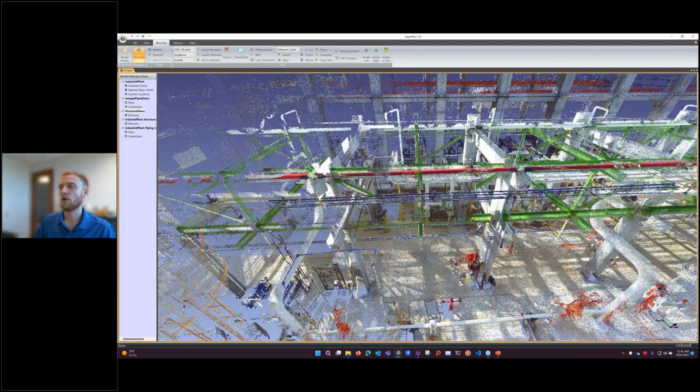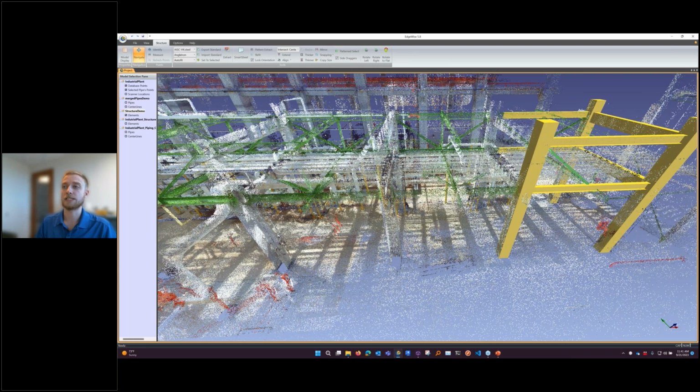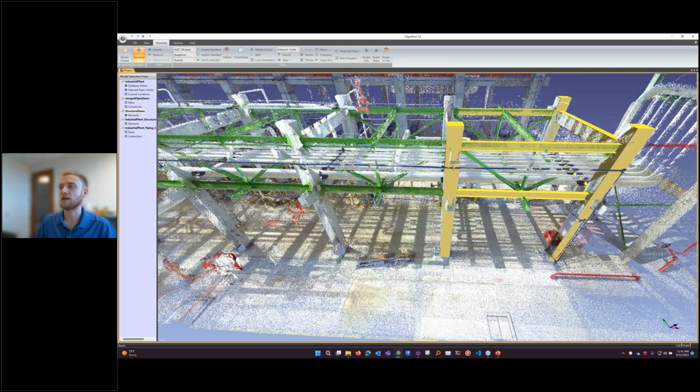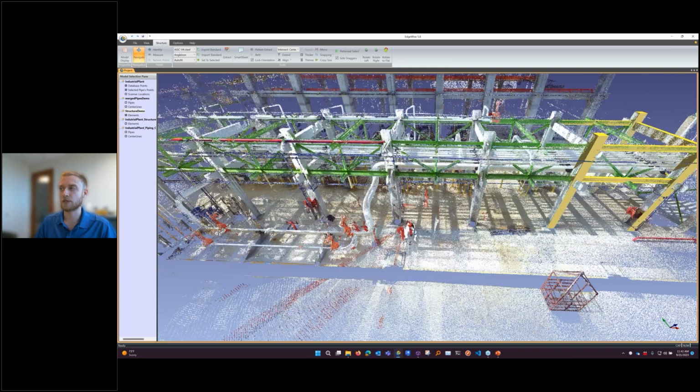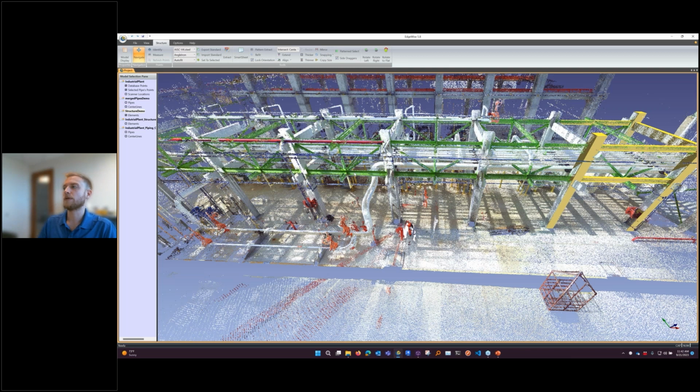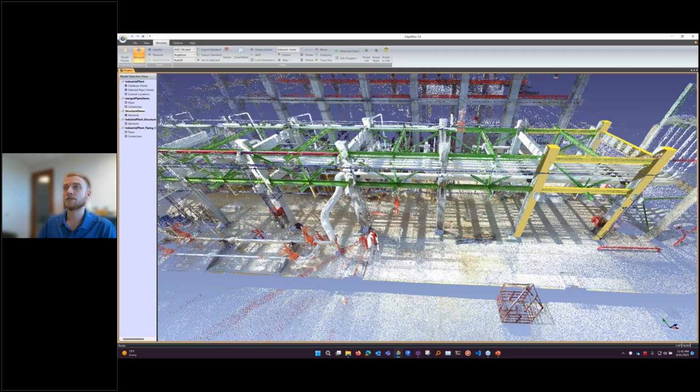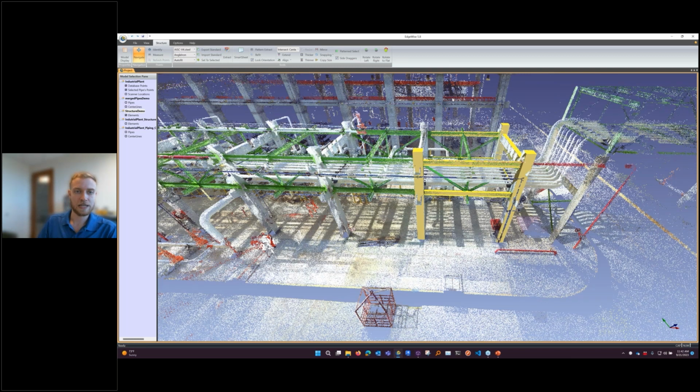And so instead of going through and extracting every single one, which would still be very fast because I can sit here and extract in this one view, I could extract every one of these angle iron and I-beams. I could do a ton of extractions right here without having to move, especially if I start doing section boxes and things like that to isolate point clouds. You can move very quickly extracting one at a time, but we also have pattern extract, which is going to try and automate that even further by leveraging the fact that there is repetition.